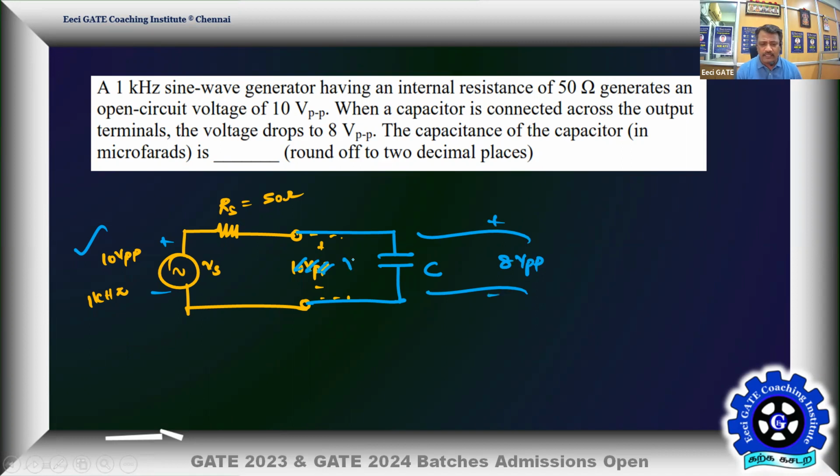Let me call this my V0, and this is my Vin. So this is Vin of s in the s domain, and this I can call V0 of s. We can find a simple transfer function connecting the two, V0(s) by Vin(s). Since you are familiar with it, otherwise you can straight away apply nodal potential division.